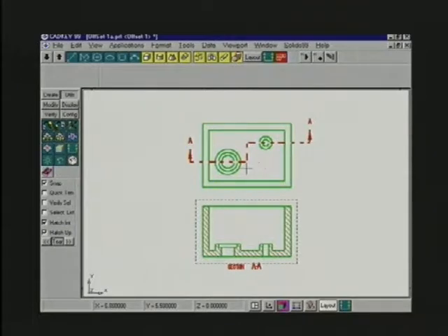If you actually cut this object with a hacksaw, you'd get a vertical line right here. And you notice we didn't draw any vertical line because this cutting plane is just imaginary. And so we don't show any surfaces that are imaginary, because there are no surfaces. This is an imaginary cutting plane, but we've offset the cutting plane to pick up additional features. There are a lot of times when the offset section is a very powerful way to reveal interior details on an object.